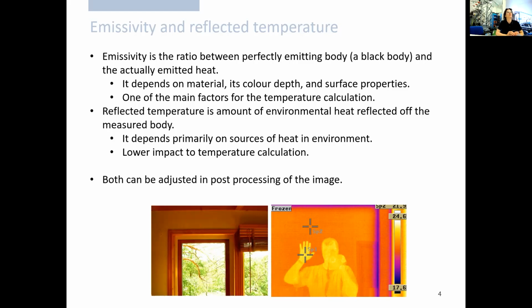The emissivity can be estimated to the level of low, medium, or high by looking at the object. The color depth and the surface, whether it's matte or shiny, can tell us something about the emissivity of the object. But since we usually can't tell what material it is, we can't estimate more accurately than this. For more accuracy, we have to measure the emissivity, which can be done quite easily using a dark tape and a camera, or the emissivity values can be looked up in the tables.